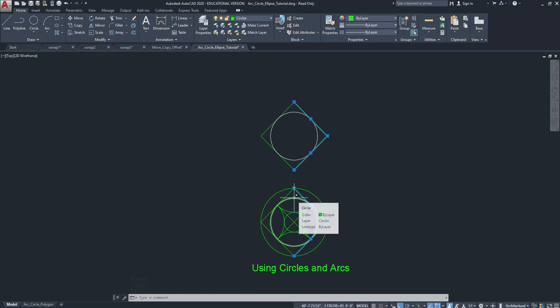Okay, and we don't know arc yet. We're going to learn arc here in a second, but I have these crossbars that I need to create. And so line, I'm going to use, oh, there's a midpoint, right? Good job. Midpoint to midpoint. Escape, enter, or sorry, line. Click, click, there we go. I've got my crossbars going there, right?